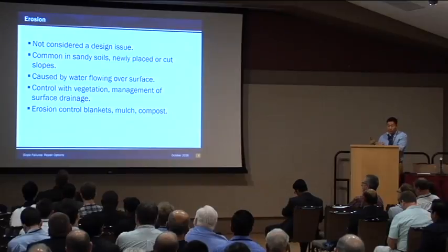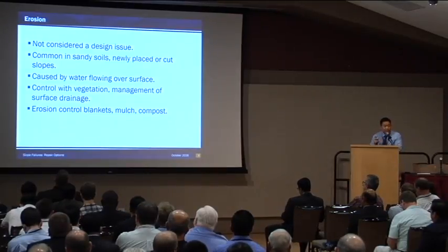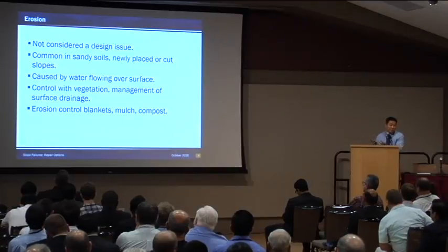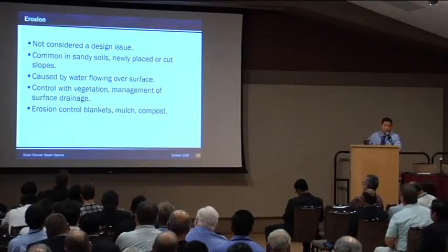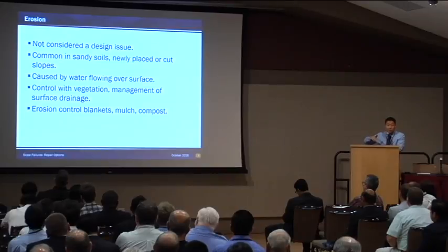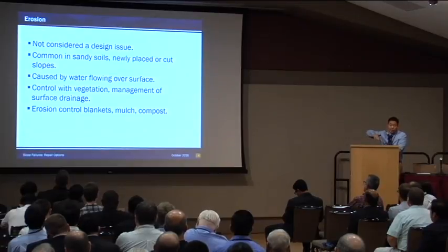So you can divert the runoff. A concrete curb is very good and very cheap for diverting water. You can use the concrete curb, or a concrete flume, or you can put in a shoulder drain, especially at the end of the bridge or the approach of the bridge. So you can put the shoulder drain at the approach.